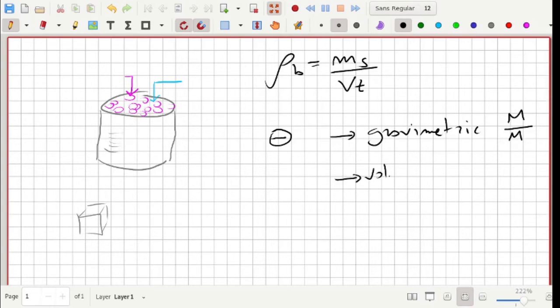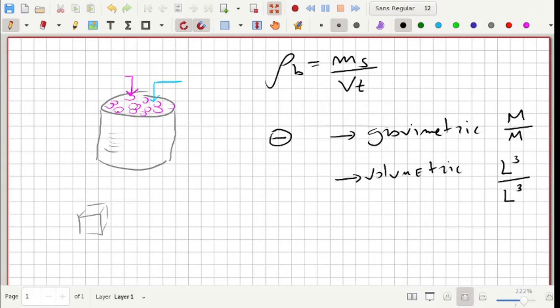And we have the volumetric water content, which is the volume of water divided by the total volume of material. So volume of fluid over the total volume. Again, it doesn't cancel because we're talking about different things. In other areas, the volumetric water content could be represented as a percentage, but percentage is not recommended, at least in soil science. I don't really have a big problem with that, but let's consider that when we're writing our code.